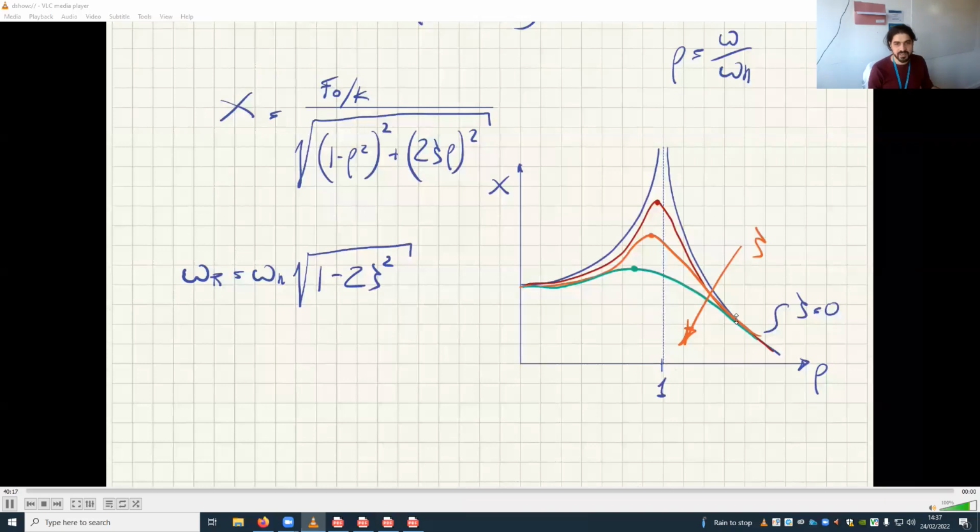If you want to break a wine glass, you play a sound, yeah, exactly. So if you want to break a wine glass with a speaker, what you do is estimate the damping ratio of the glass. Then you find the resonance frequency of the glass given the damping ratio. And then you can just play a pure tone, which is a sine wave, at that frequency. It might not break, but it will give you the largest possible amplitude at that mode shape. Now, whether that's enough to break it depends on the damping.